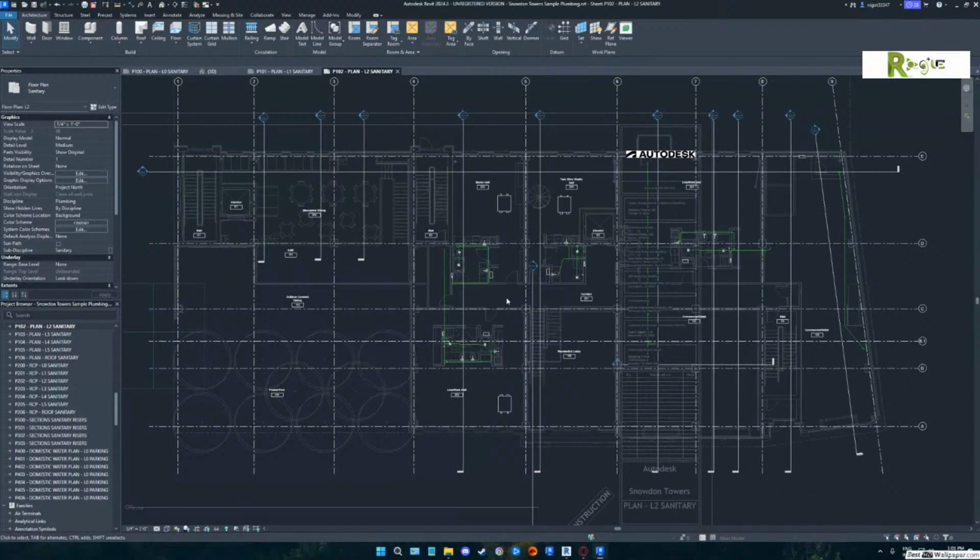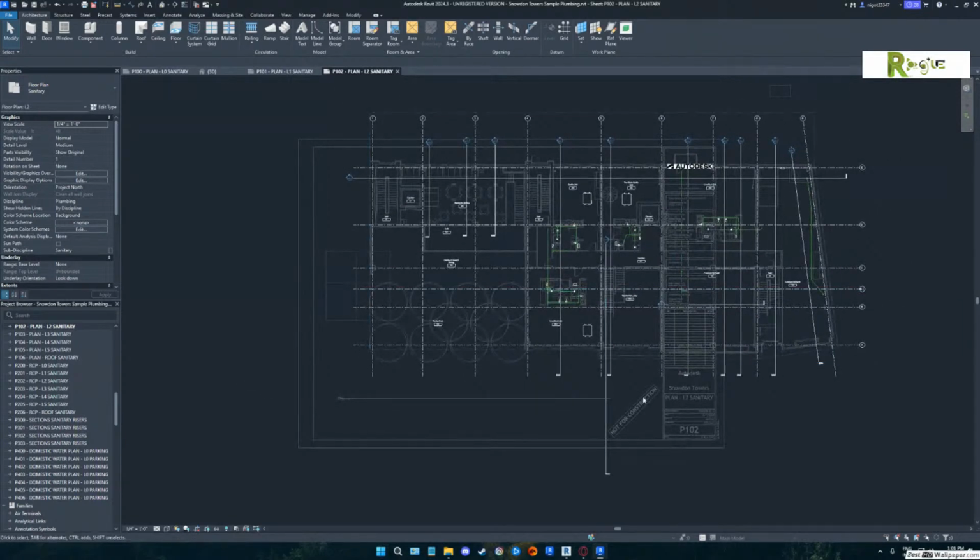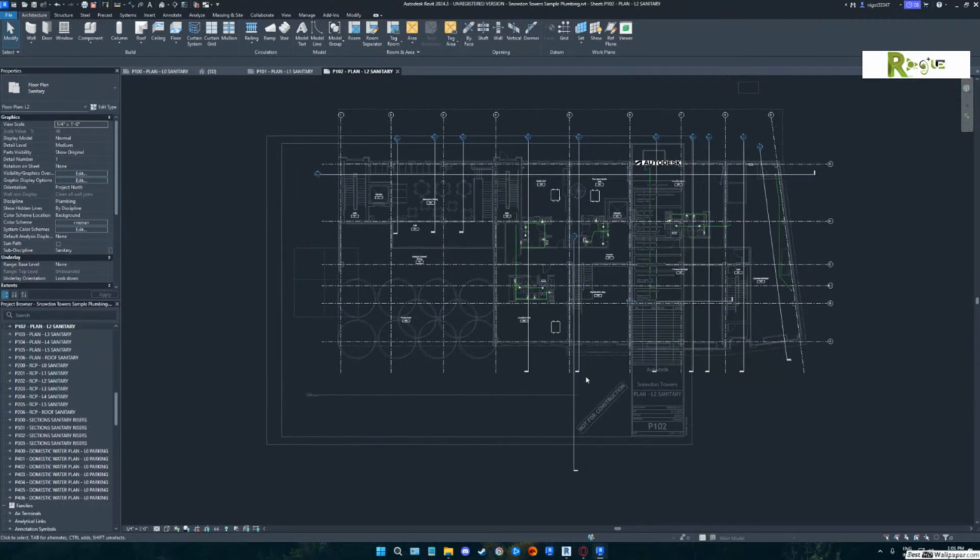Now, do you see the problem with the scale, though? With that scale, it doesn't fit on the sheet. That's why they made it an 1/8" scale. So how do we make this into 2 quarter scale drawings to fit on 2 sheets? Eric, can you walk them through it? We're going to need to break the plan in the middle and have 2 separate views set up for it.